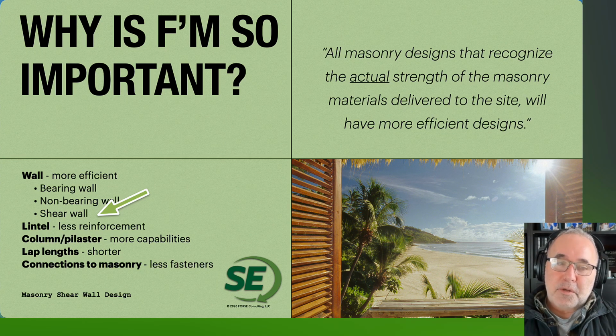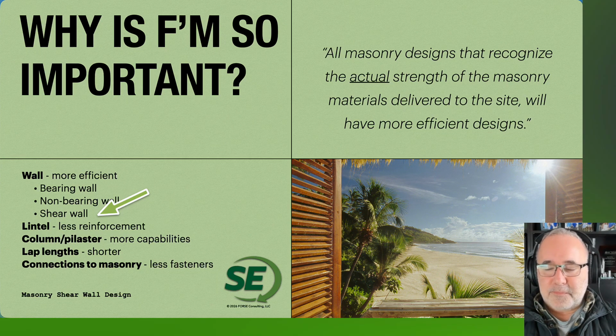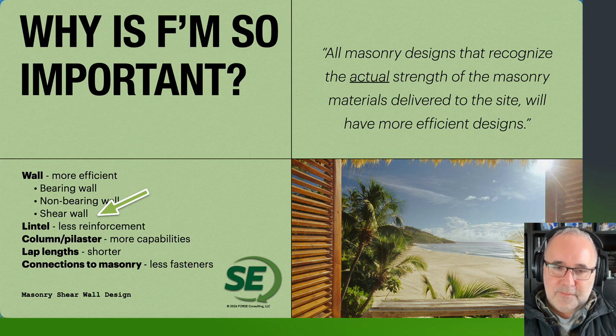That doesn't mean that we should arbitrarily choose a higher strength F'(m). What we should do is find out what the materials are local to the site, at least understand what the available strength is, start with that as a baseline, and then work up from there.